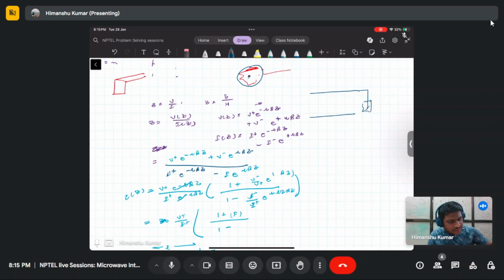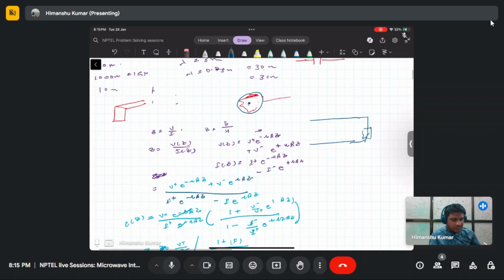Actually, for a coaxial line and the two wire line, the impedance is basically the ratio of voltage and current. And if you consider waveguides and those things, because there is no definition of finite current there, you define the impedance as the ratio of electric and magnetic field.